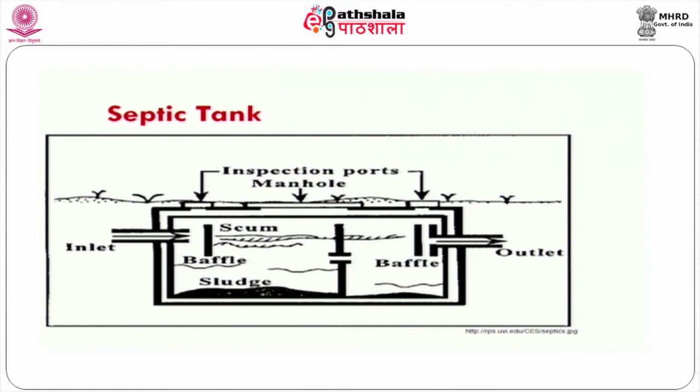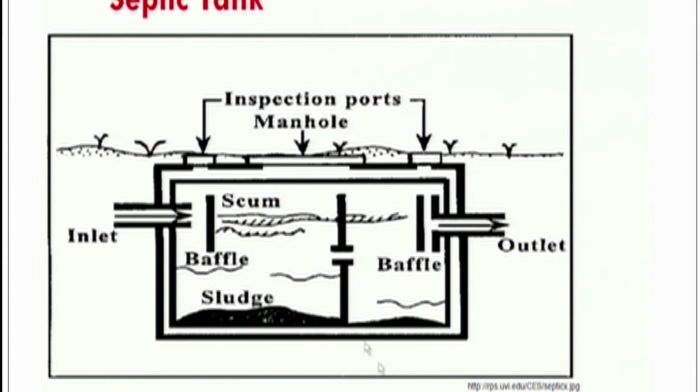While designing the first compartment, we have to provide adequate space to accommodate raw sludge, the influent suspended solids. Whatever soluble organic matter enters this reactor will undergo anaerobic decay. At the end of the anaerobic reactor, due to liquefaction as well as gasification, the organic contaminants are converted to gas and liquid.